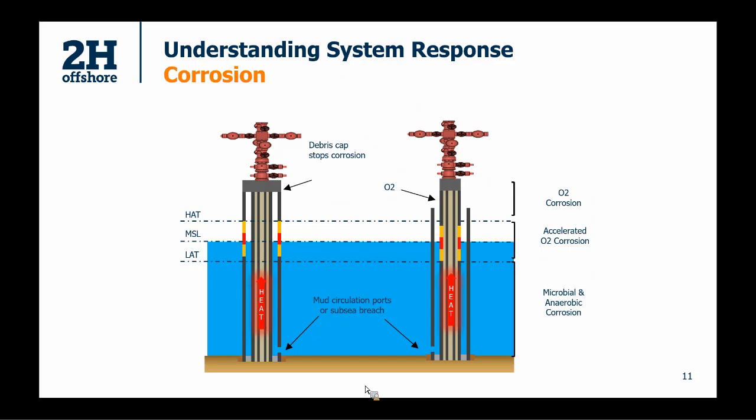But it's also worth noting that if you have a well integrity issue somewhere else in the system, can that then lead to a secondary problem somewhere else? On the right hand side, you have a system that's a casing supported system. So your conductor isn't a structural member, your casing is the structural member. And if your system is working as you would expect, you have inert water in your A annulus and you're not necessarily concerned about particularly high levels of corrosion in your surface casing.